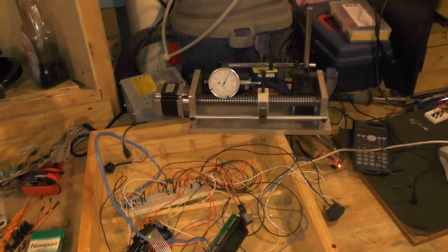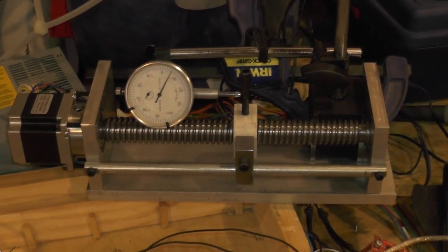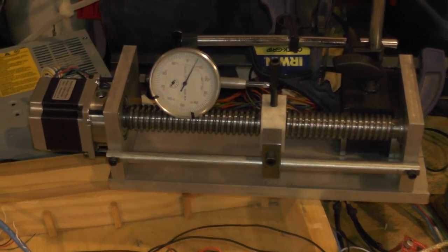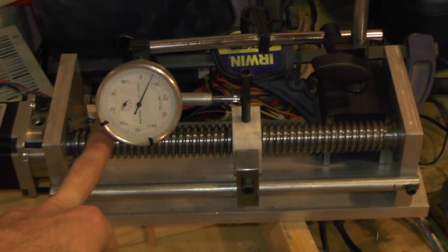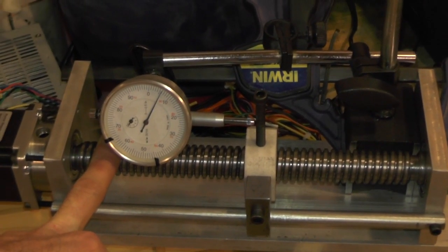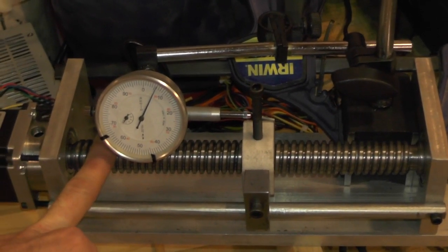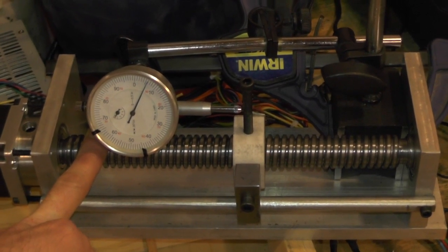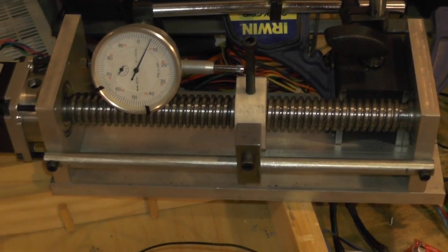What you see right here, this contraption, that's simulating the head on the milling machine. The lead screw right here is roughly the same pitch as the one in the machine. The machine's a metric one. For a full revolution, I believe it travels 196 thousandths and change. I didn't feel like setting up the lathe to cut metric threads, and they're a bit of a pain on that lathe. So this one I cut at a 5 pitch, it was just 200 thousandths per revolution.